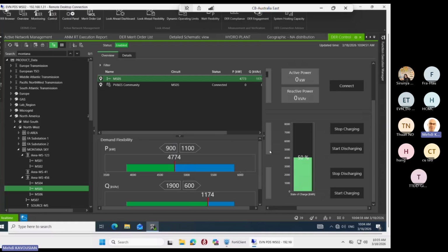Yeah. So let's say, in your case, probably you don't have a contract yet. People have solar on their system, their inverters generate 5 kilowatts right now. And you have a contract with them: I can drop you to 1.5 if I need to. From 5 kilowatts down to 1.5 is 3.5. So that's the flexibility you can play with. That's one solar. If you have a feeder with 100 of them, all the same, 3.5 multiplied by 100 is going to be 350. And that's actually here because you can curtail